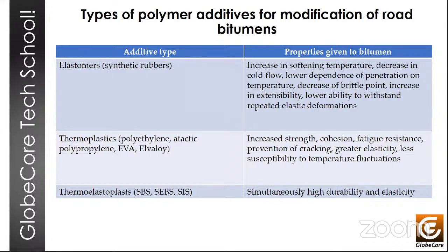And we're talking a range of 3 to 5% by weight of bitumen. The use of bitumen modified with an SBS polymer in the asphalt mix provides the road surface with the ability to quickly relieve the stresses that arise across the surface due to traffic loads.